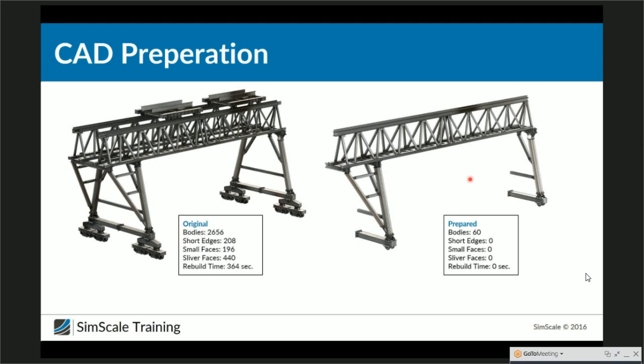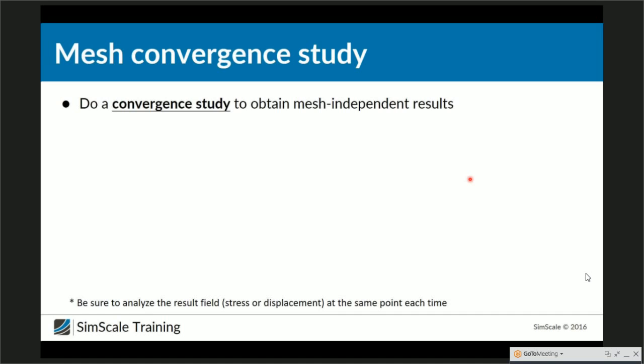A very important point is the featuring. What you can see here is a part of, I think, an assembly. And for the real part, for sure, this is modeled in the original model as a bolted joint. If we want to do a simulation here, this is again a very good example for critical parts only. We know that the last things which will fail are our screws or bolts. So we can remove the bolts, remove the holes, and this will simplify the meshing and the simulation very much. Finally, and this is very important, you should also think about how you want to create a simulation during the CAD modeling.